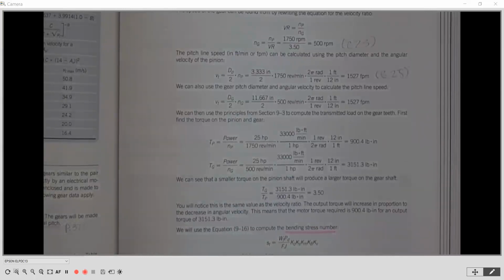There's a longer lever arm due to what? Larger diameter, so that radius of rotation is larger, right? So the same force is being transmitted from one gear to the next, right? Tangential force, but we now have a longer lever arm, our radius on that gear. And that's why we slow it down.